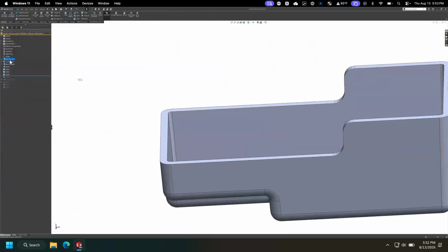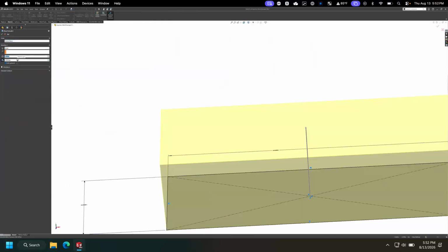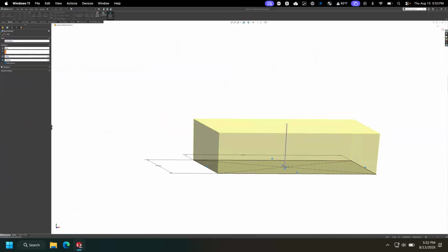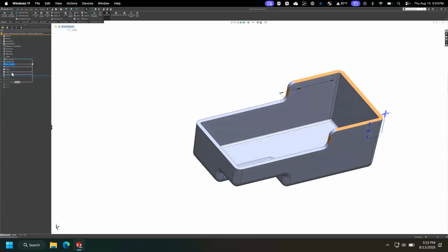Tell us what the draft is. Yeah, so with the bosses, I think everything's at a 2-degree draft for reference. So we're designing in this case with the draft in there. A lot of times I also like putting drafts as separate features because it makes it a little bit easier to see from the feature tree where it's doing that. Now, this is a very simple part, and this is just how they decided to do it, but it's certainly a thing. And there are some external drafts, and the reason for that, actually, if I scroll up here for a second.